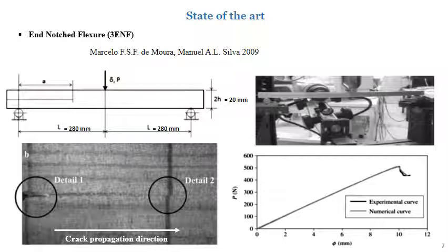2 sheets of Teflon film were inserted between the two surfaces of the initial notch in an attempt to minimize the effects of friction. The mechanical tests were performed in a universal screw testing machine Instron 1125. The specimen was supported by 2 cylinders and loaded at mid-span with a traverse speed of 5 mm per minute. The applied load and displacement values were recorded during the tests.